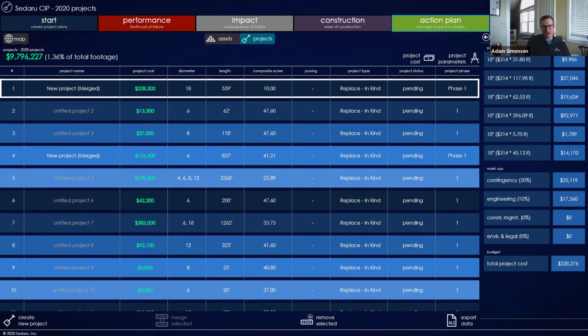Right. So I could take my operational score out of the PACP database, my structural rating that comes out of there. I could use a quick rating. I could use the number of defects or certain types of defects. Yeah, all those sort of features. And you also could pull in criteria like D/D ratios, or flow capacities as well, and use those pieces in there too, right?